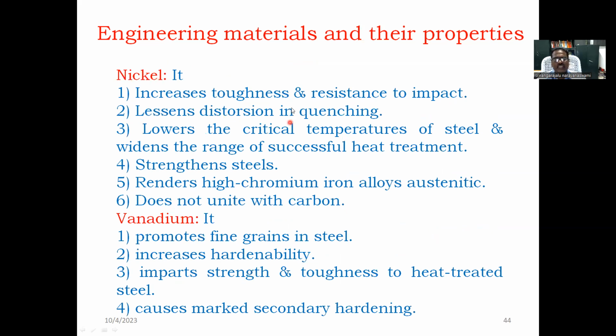Nickel increases the toughness and resistance to impact, lessens distortion in quenching, lowers the critical temperatures of steel, and widens the range of successful heat treatment, strengthens steels, renders high chromium iron alloys austenitic, and does not unite with carbon.